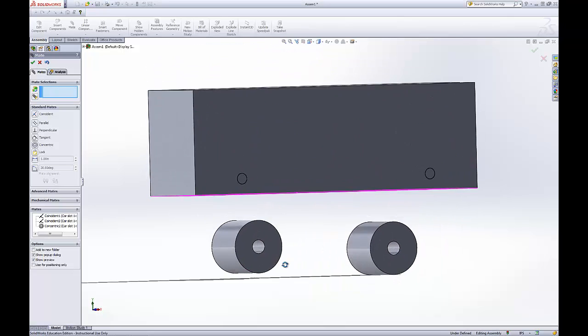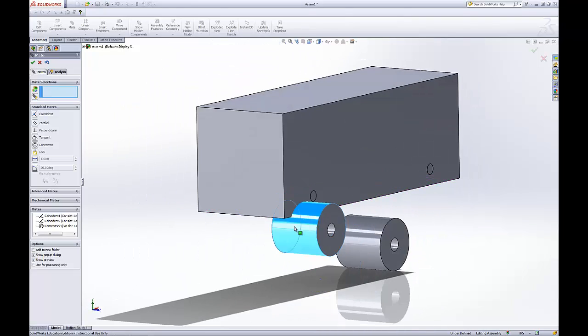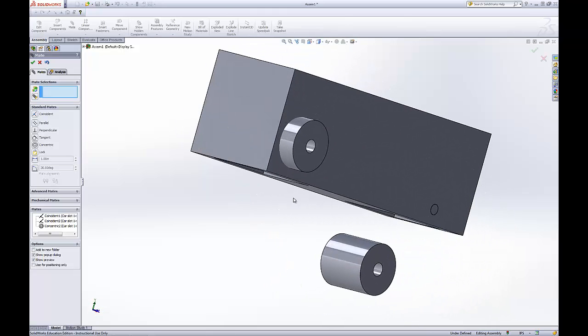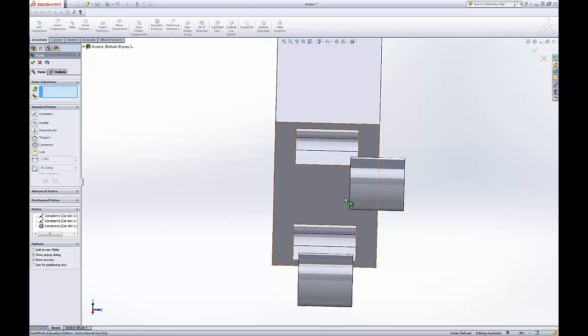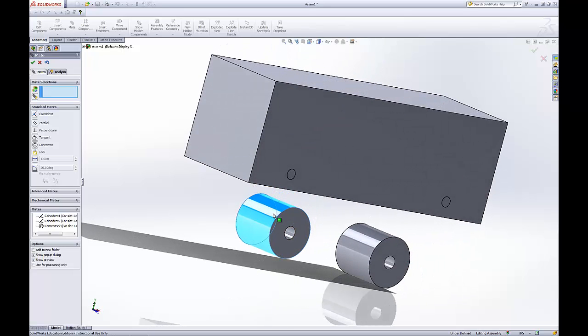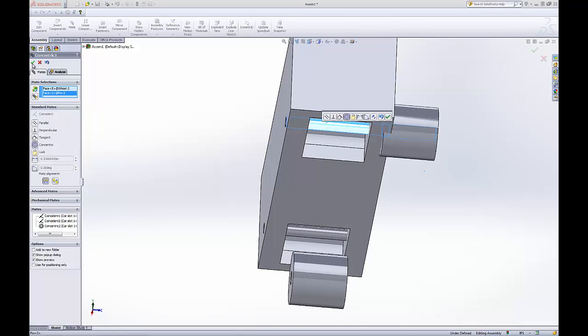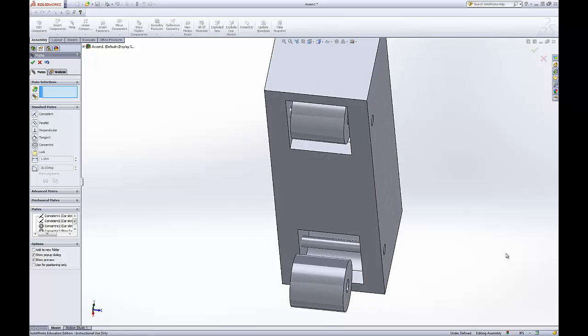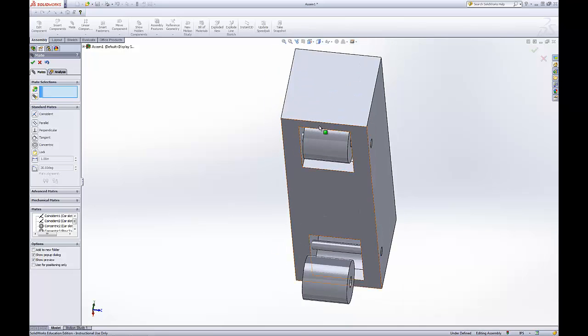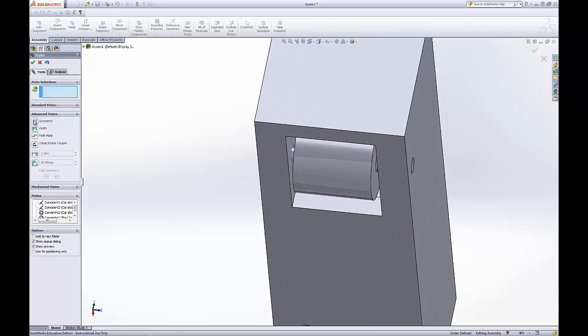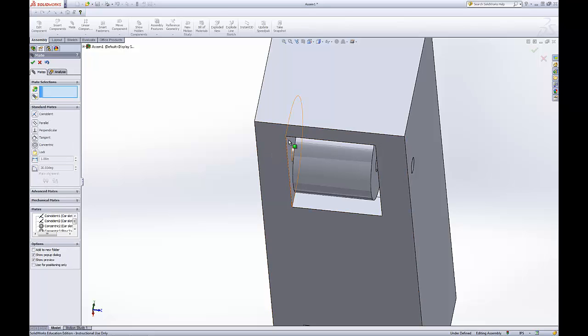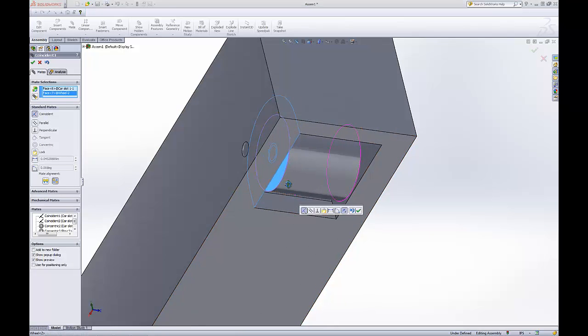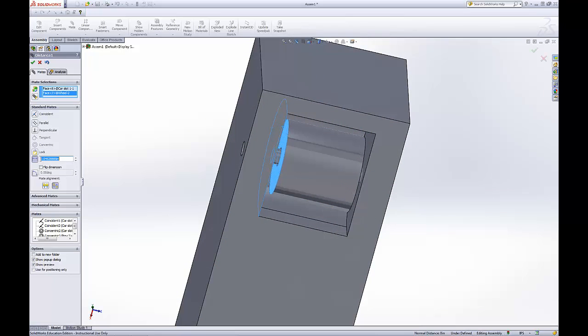Okay, so now we have the pins in place. Because of SolidWorks, we can defy gravity and defy physics. It really doesn't care at this moment, so it helps for aligning things up. So now we want to get this cylinder and that cylinder together. Now we want this centered here or off the wall at a specific distance, so we're just going to do the basic constraints. You could probably use a symmetrical right here, but we're just going to keep it simple by clicking on that face, clicking on this face, and now they're touching each other, but you can use this to move it a very small distance away from the wall.